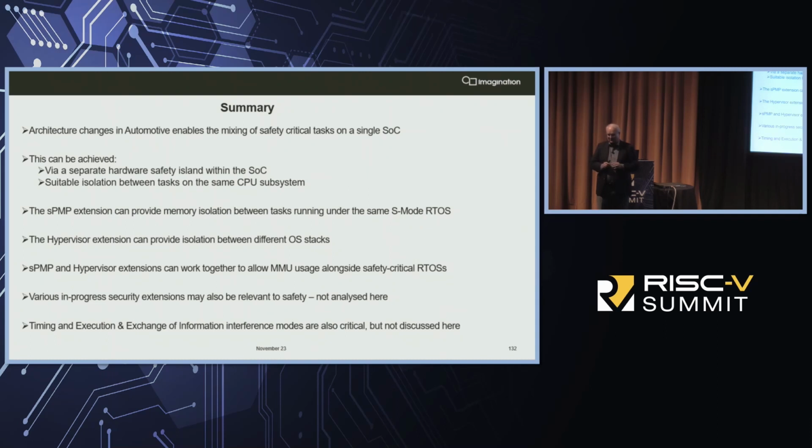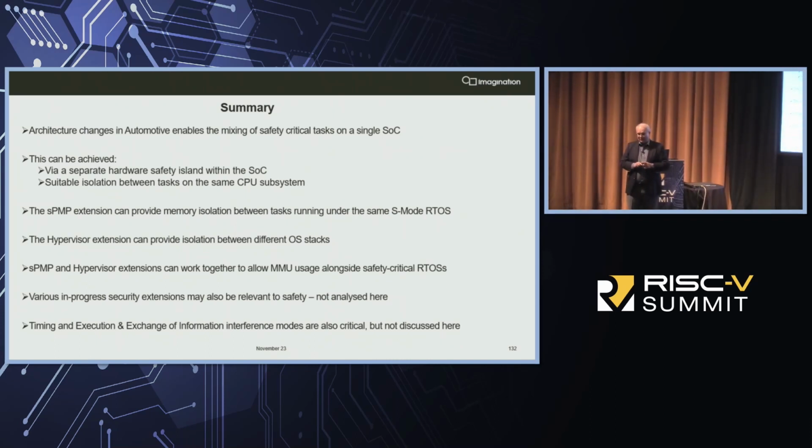This is not strictly something which is about automotive systems and ISO 26262. You can have generic hardware, but if your hypervisor on top of that is at a certain level of evaluation, for example, you would take Common Criteria evaluation level 5 or 6, then you can run applications on top of that that will be protected underneath the certification level of that hypervisor. Okay? All right? But you will have a certain number of underlying hardware requirements. Okay? You will, for example, have requirements such as a secure boot, a root of trust, and things like that. You will have requirements on your memory management systems. Okay? And here, the SPMP extensions will help you with that.